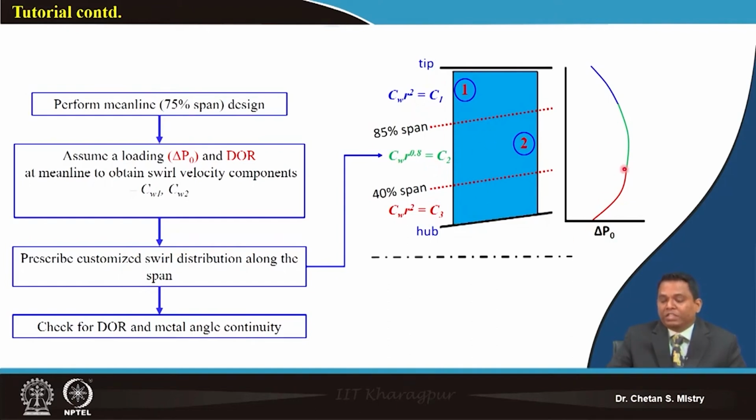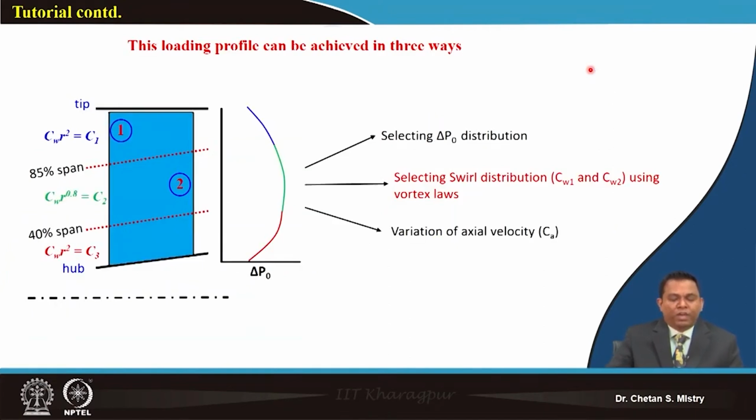So you can say this is what we are looking for in the sense of our distribution. We are expecting our total pressure ratio of 2. So in this particular region we will be loading on the higher side near the hub region, and near the tip region we will be loading slightly lower. This is very interesting, and this is the design concept which people are adopting these days. So if we are configuring this, there are other chances also.